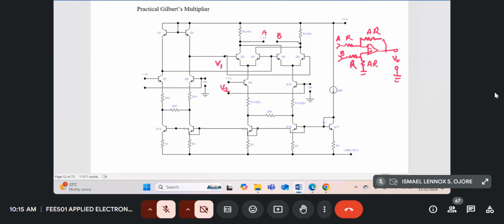Now, I'll still only concentrate on the Gilbert's multiplier cell and its associated circuitry for the time being. The preconditioning circuit, which comprises Q7, Q8, and the constant current source Q13, and I think Q14 there, we're going to leave for the time being. I'm only going to concentrate on the Gilbert's multiplier cell because there you can see the different ways of generating the constant current source.